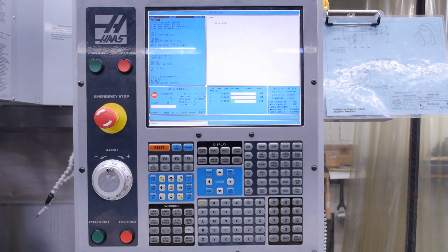As noted on the TA outline, step number 3 is optional, and it should not be used by TAs who have given the demonstration for less than 3 semesters. Step number 3 tells us how to override the safety switch on the CNC Machining Center, but this is only a function that experienced TAs who strongly understand the necessary safety to run the machine with this switch disabled can use. Step number 4 tells us to press the blue power-up restart button to initialize the machine servos.